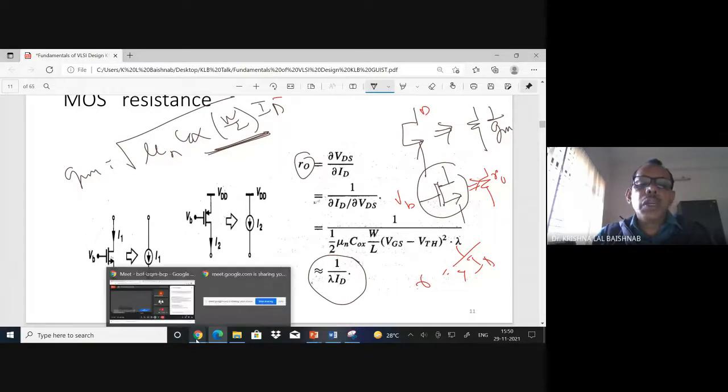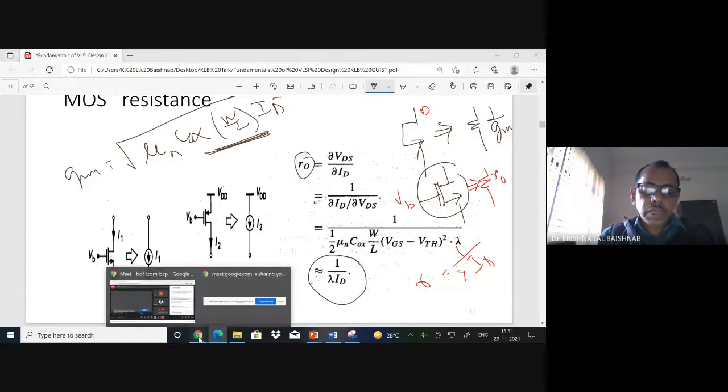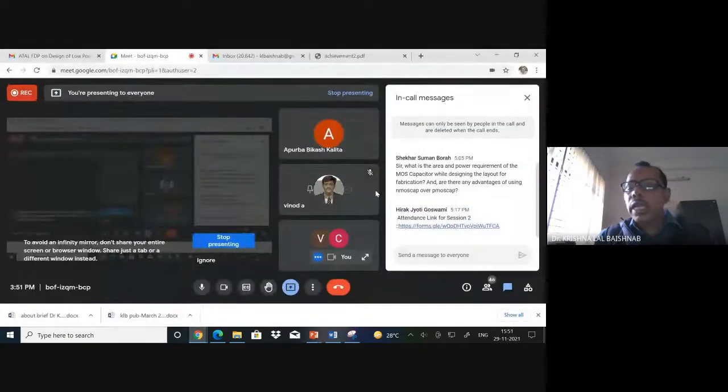But your design may not permit a minimum area, or it may demand a higher area because you need gain. Gain means I need a high W by L ratio. Okay, W by L ratio, not area. The W by L ratio should be high. That is the context.